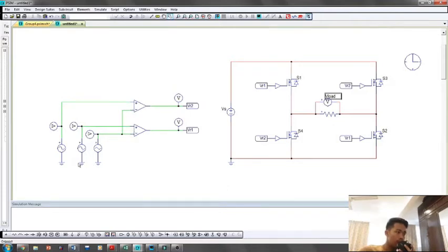it is low. The interaction of the waves determines the switching instant and commutation of the modulated pulse. This pulse will be sent to the power switches in order to turn on and turn off the power switches. The frequency of the triangular carrier wave can be modified from a lower frequency to a higher frequency. If a higher frequency is used, the number of pulses per cycle will also increase. At the same time, it will reduce the harmonic content of the inverter.